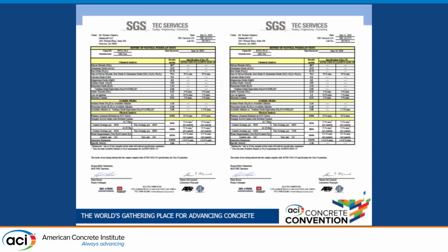Here we have ASTM 618 certification. It's a little blurry because we have both the 4 micron and the 8 micron side by side. But this is 48.7% silica, about 13 point something aluminum, and 12.7 iron oxide, with a general sum of about 75% of the 3 oxides.